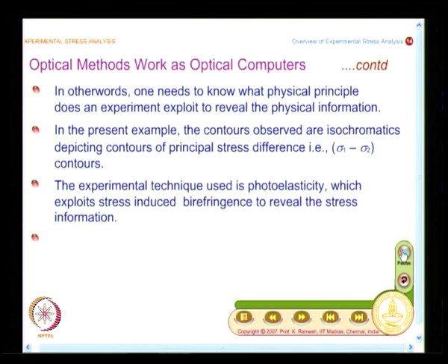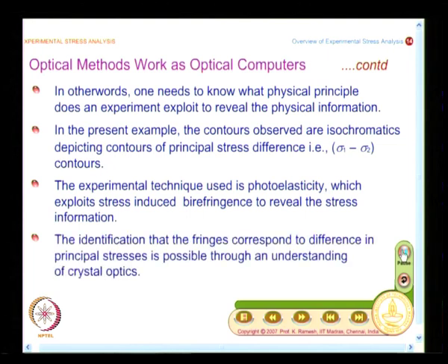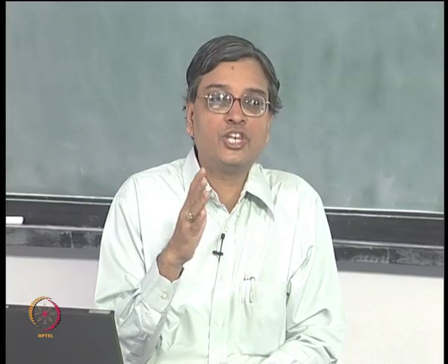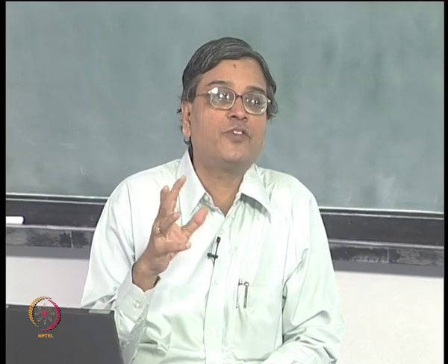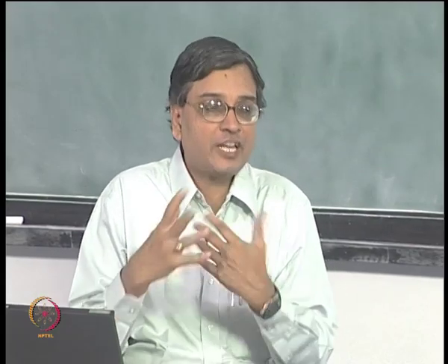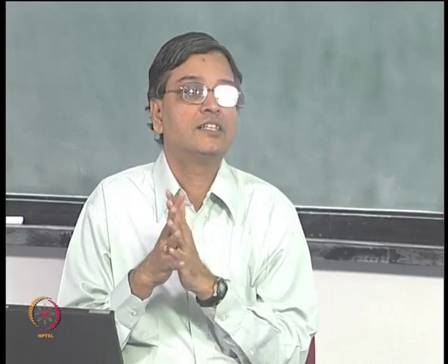And the technique that is used is photoelasticity, which, as I said, exploits stress induced birefringence to reveal the stress information. That is why I have taken a specimen which behaves like a crystal when it is loaded. That is the epoxy, which has the phenomenon of stress induced birefringence, and because stress induces changes in the optics, by analyzing the optics information it is possible for you to relate the effect of optics in terms of stress patterns. So, that is what we have done in this simple exercise.